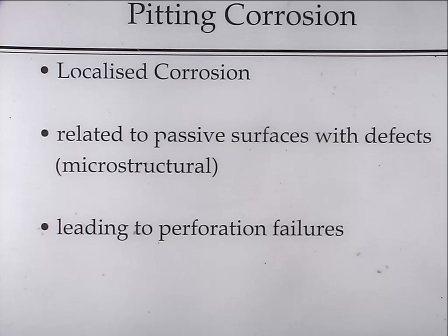After that you begin to get into bulk property, bulk microstructure material. So this pit isn't really associated particularly with the heat affected zone. It was found to be associated with the coating failure. So that's from the outside in, and then I've got a couple more from the inside out.